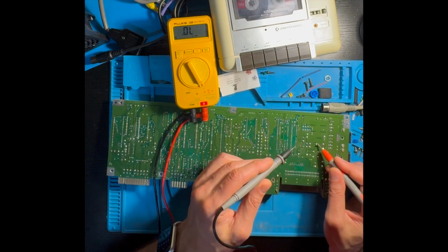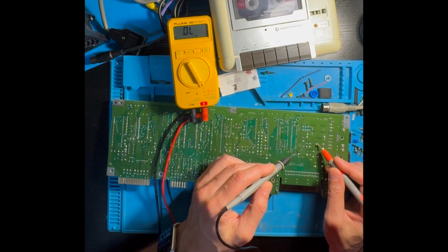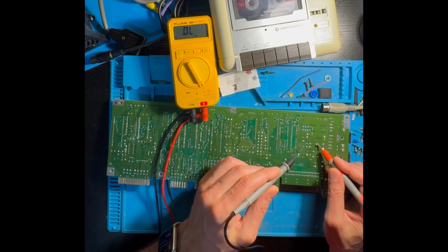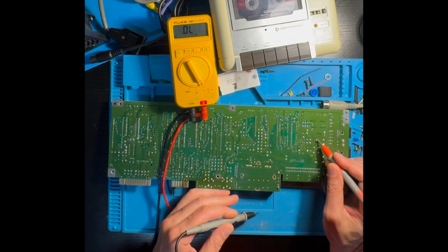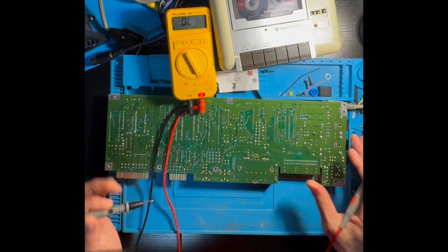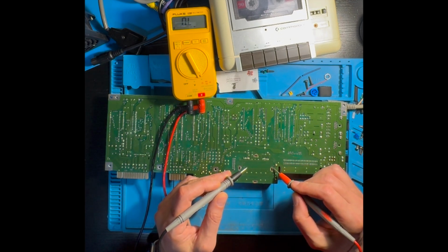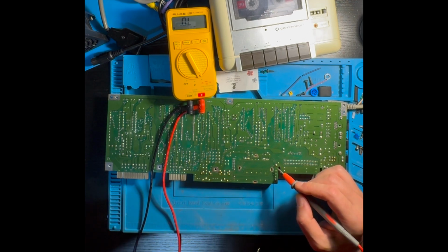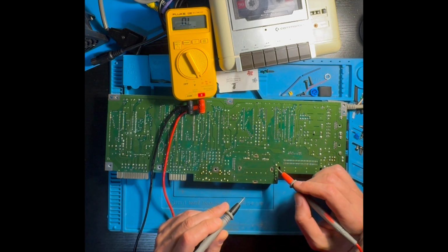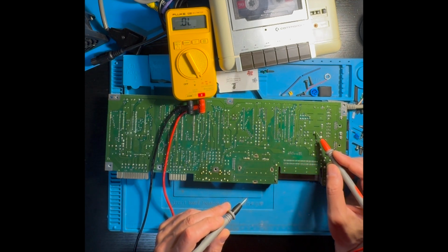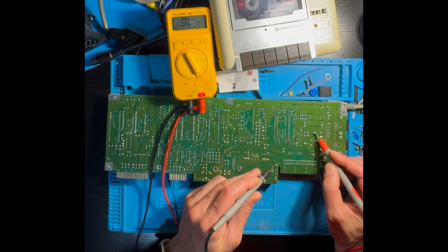And then I'm kind of looking through, seeing if I can figure out anything. And right about now, I spot the issue. And when I took this RF modulator off, I must have nicked one of the traces. And so that's the problem, because if I go from that point to here, yep, we get connection.